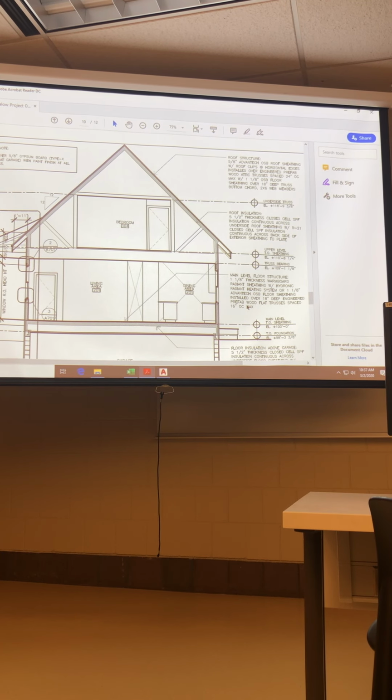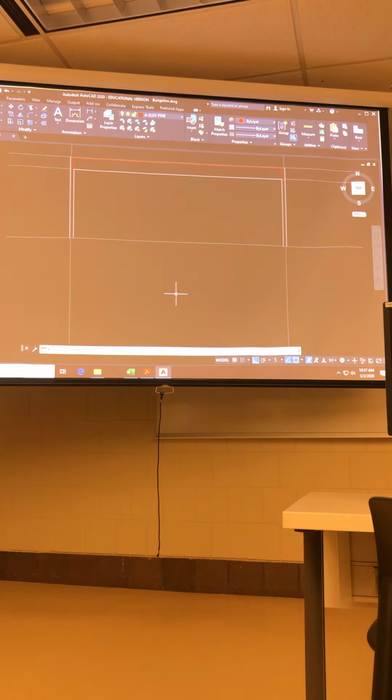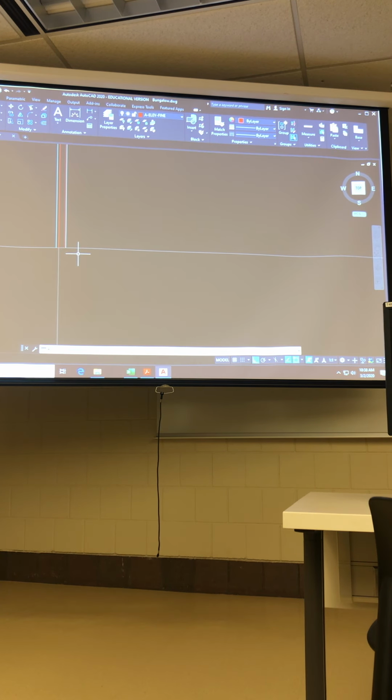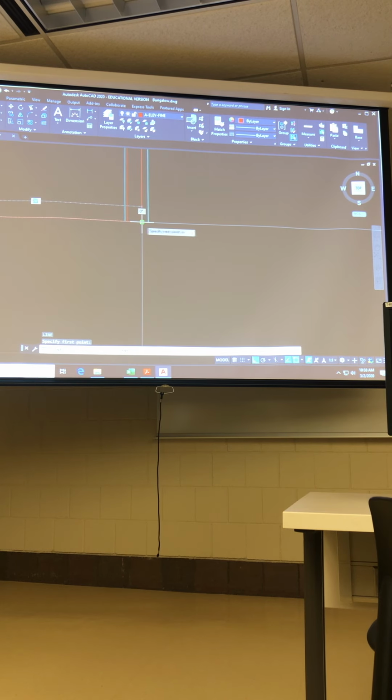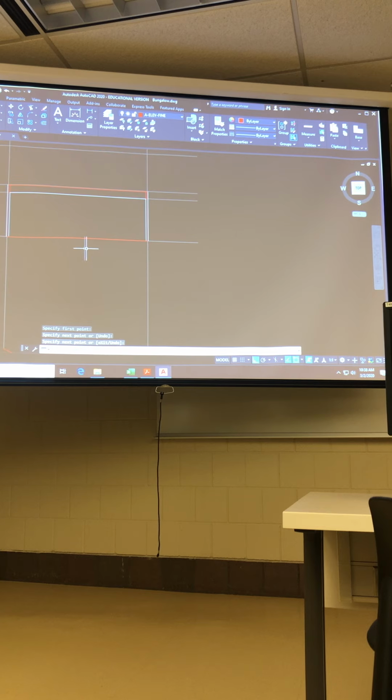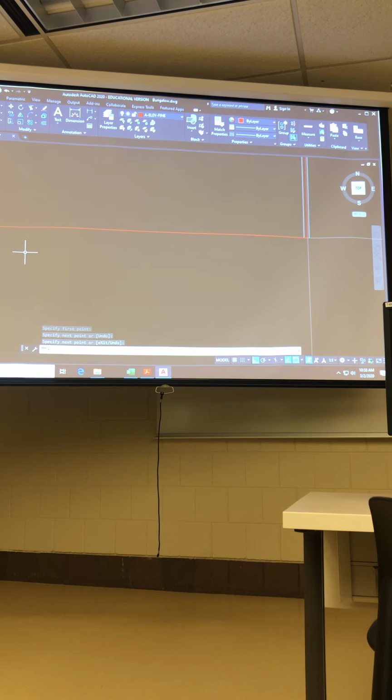Where we don't have radiant floors on the main level, we're just gonna infill those areas with 1 1/8 inch standard OSB so that the thicknesses are equal and they tie out with one another, okay? So that's a long explanation to justify what I'll do next, and that is, I'm gonna go ahead and draw another line from my outside face of framing to my outside face of framing, and that line is the top of that warm board or OSB 1 1/8 inch thickness floor sheathing, okay?